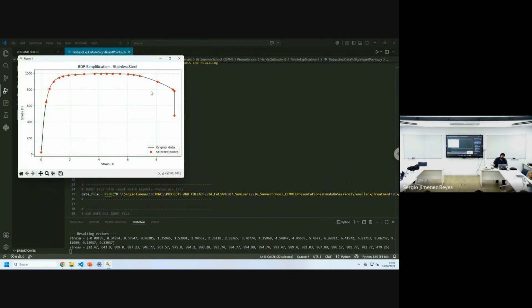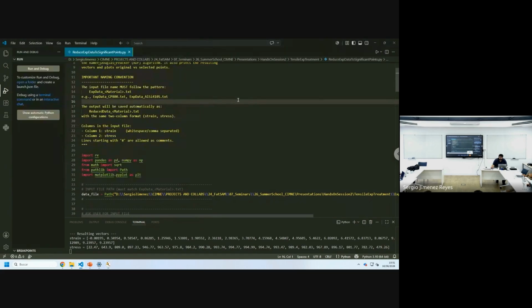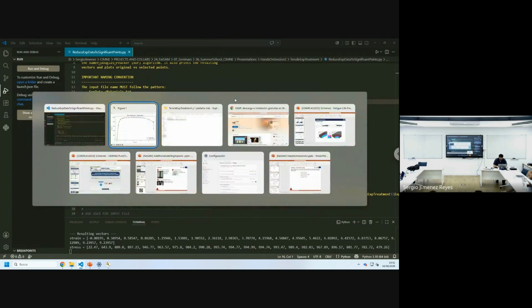So there are ways to do that. For example, as Lucia has mentioned, instead of just inputting random numbers, we developed some algorithms that do this calibration process automatically. Then from this data you select those points. For the fracture energy, as you said, you just have to put a really high one, so that for sure this value will not be reached, and then you reduce it.